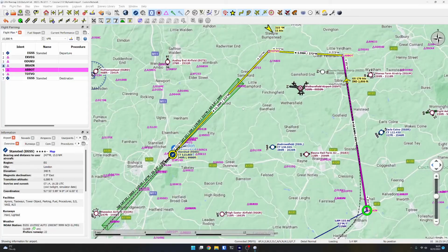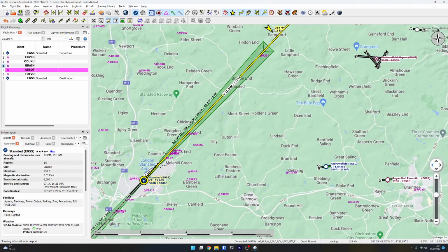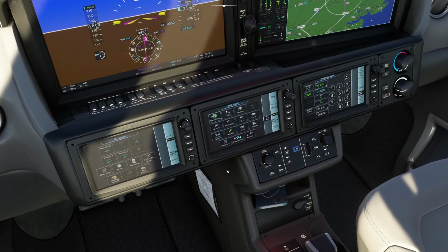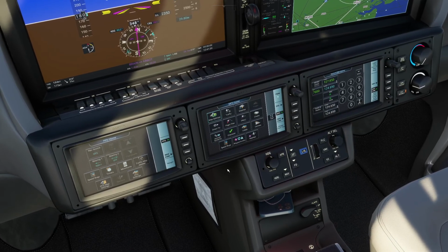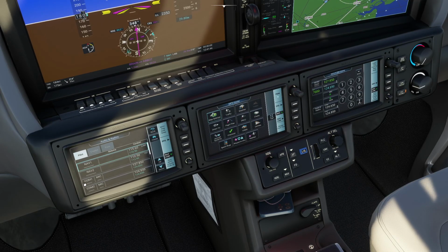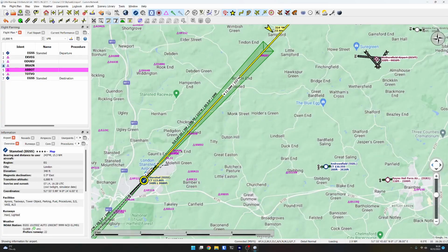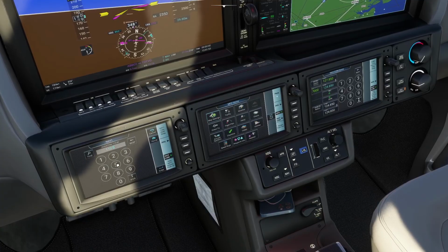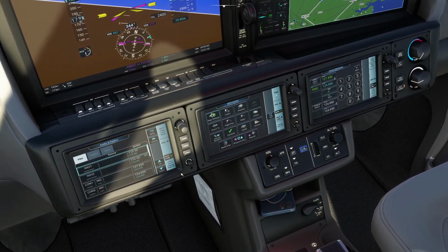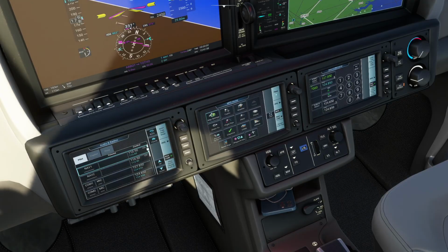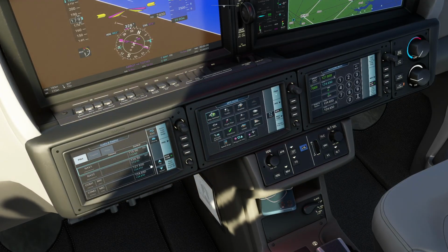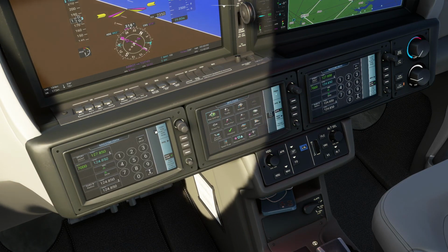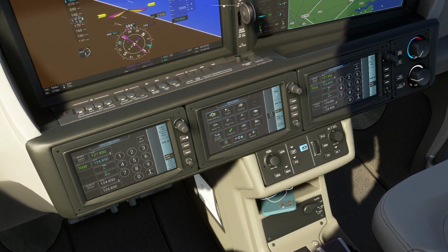And again, while we're flying around on the approach, we'll go and program in the ILS. So it's 110.50 and 222 degrees on the course. So we go to the Navcom section, radios, and we want 110.50. So Nav1, 110, it was already on there, wasn't it? 50, and we transfer it. Okay, so you can now see the ILS frequency is programmed in, and we can come back out of here. We can go back to the PFD screen.